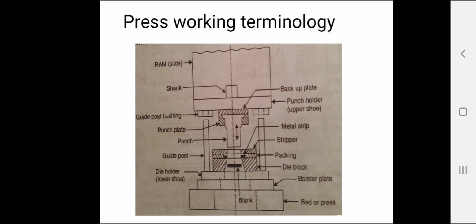There is one connecting rod known as the pitman, which is used to transmit motion from the main drive shaft to the press slides. Then one more important thing here is the height and stroke. What is shut height? Shut height is the distance from the top of the bed to the bottom of the slide with its stroke down and adjustment up.